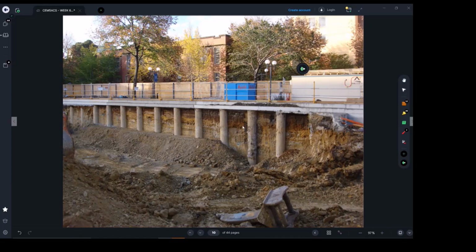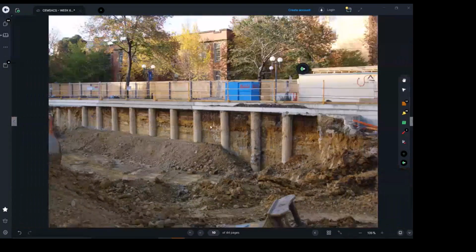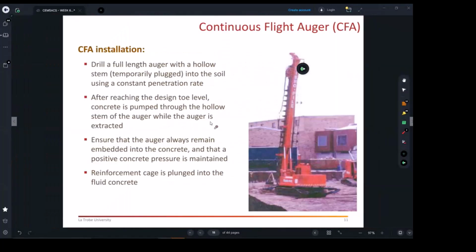One of the things you need to recognize as a difference from driven piles, as I said, is that driven piles usually reinforce the soil, to carry the road or to carry a tower. But with these, you will have the opportunity to place a shotcrete wall between the piles. With the other options I was talking about, it was not for a retaining wall. It was basically for taking axial loads, future axial load.